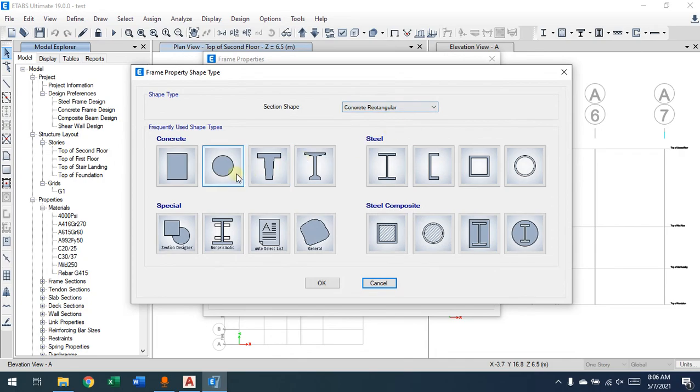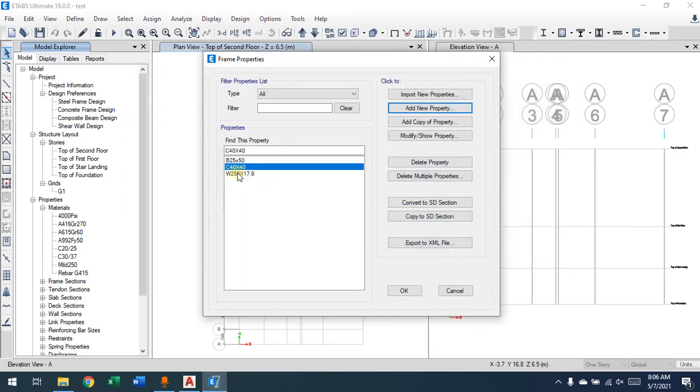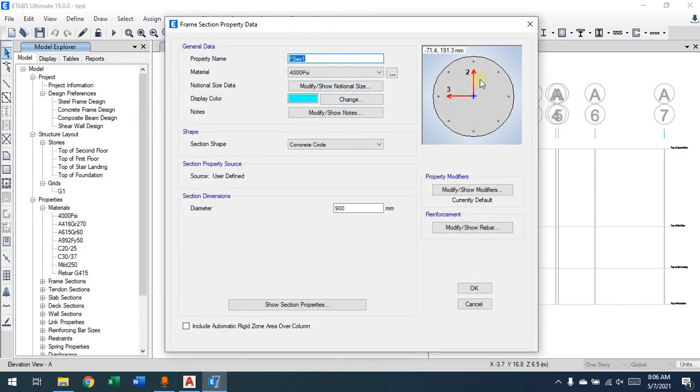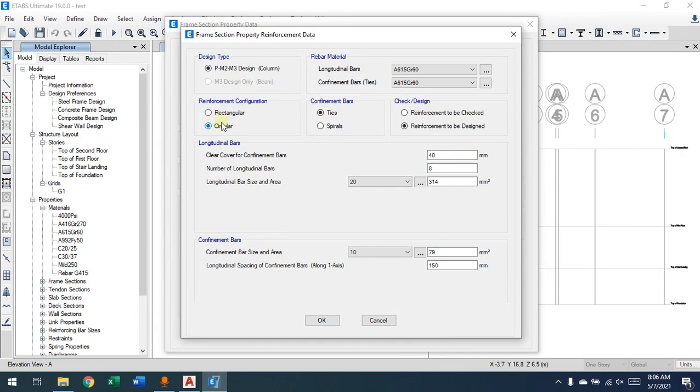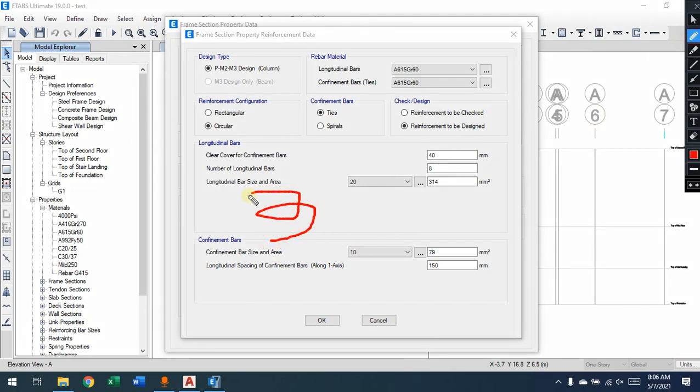Do you have many more? Yes, you have circular. I mean, you can go still OK. Basically, if let's say we choose this one to be column, if you go show rebars here, it's circular basically. So in the circular you have spiral reinforcement. You've maybe seen them. The spiral is like this. The tie will be like this. It's much stronger than a normal tie, one by one. So spiral is much stronger than the single ties, sometimes used in the circular columns.